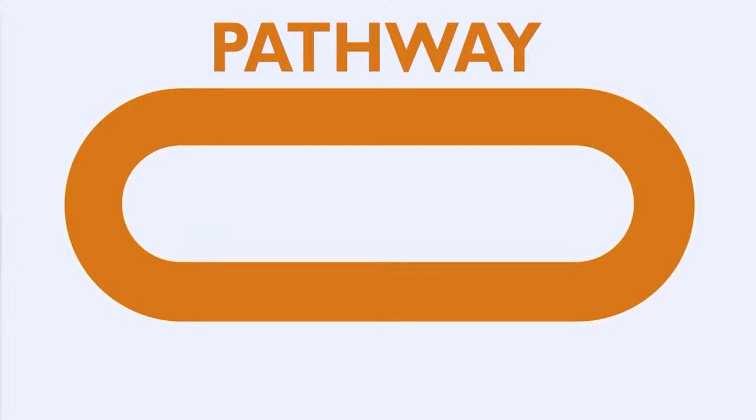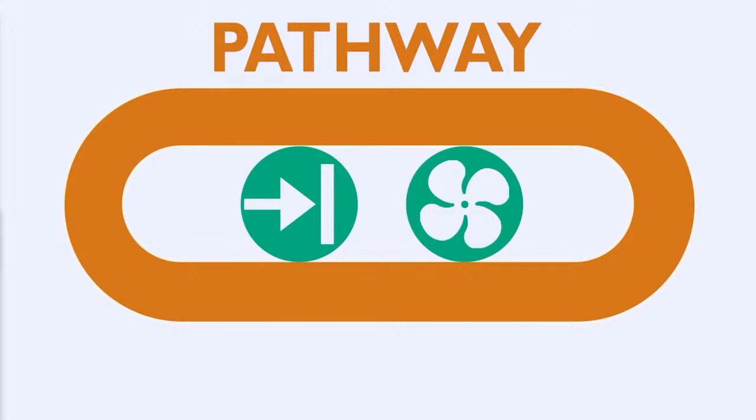Pathway. A pathway management solution breaks the link between the contamination at the source and the building occupants by two primary means. Barrier systems, which physically block the passage of harmful liquids or vapours either at the source or the receptor. Dilution dispersal, where ventilation systems are used to reduce vapour concentrations below harmful levels. Ensuring barrier and ventilation systems work effectively over the lifetime of the building is critical. Both specification and installation of these systems is more complex than it may appear, with an array of physical properties, tests and installation details to consider.